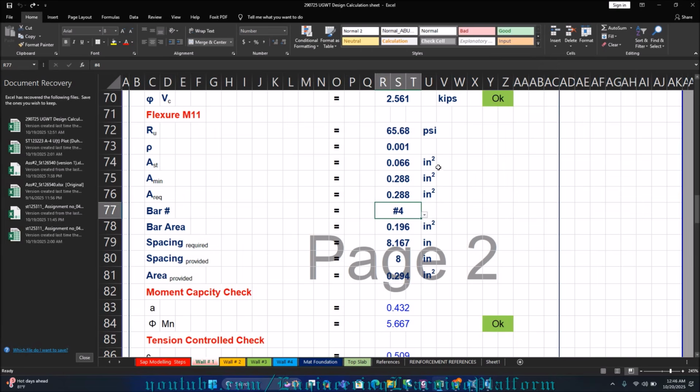Guys, see, as far as this video is concerned, we are not doing an economical design. We are just designing it. Okay, if it happens when you have to design it economically, then by looking at the moments across the whole section of the wall, the complete wall, we can play with the reinforcement in quite a smart way, and we can reduce our reinforcement amount. But that's not our goal of today's video. In today's video, I have to show you how you can get the reinforcement from the moments from SAP2000.